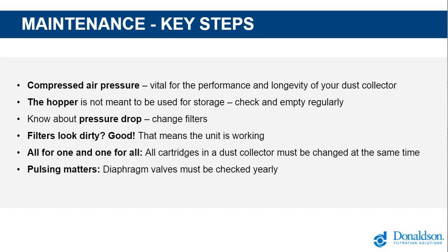And then moving on to pulsing matters as well. Diaphragm valves must be checked on a regular basis. They're a key part of a dust collection system. How many of us have walked past a collector where it has maybe, say, 10 valves? You're hearing a sequence of them pulsing, and there's a totally different sound to another diaphragm valve. That has then failed. It has ruptured at that point.